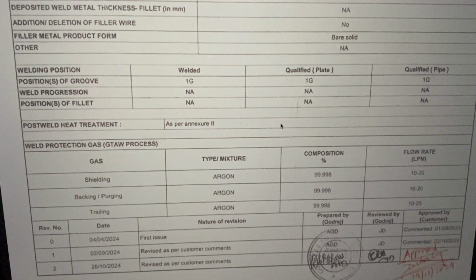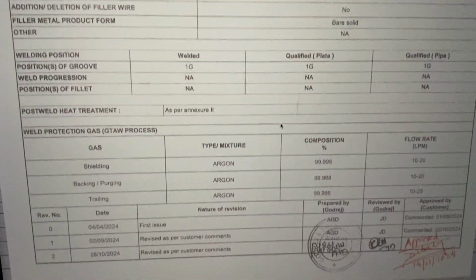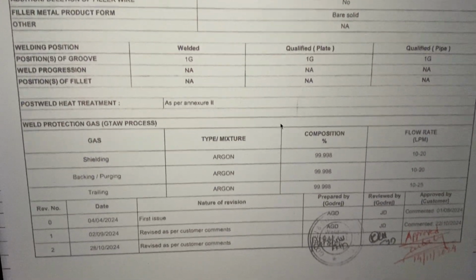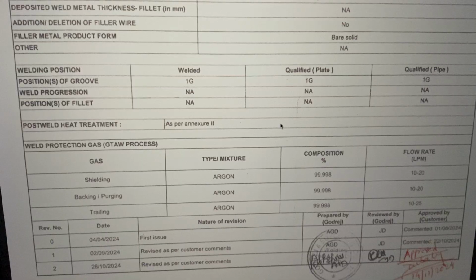And to remove that, plus the stresses, as the weld is going to be in liquid form and going to shrink, we cannot avoid the shrinkage stresses in the weld, and that's the reason for deciding a post weld heat treatment, whether it is solutionizing, whether it is stress relieving, or if we want to achieve certain properties.